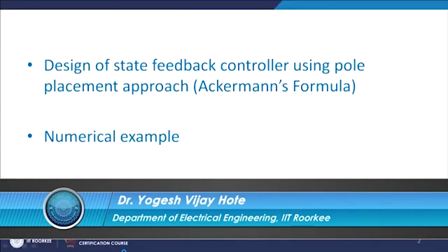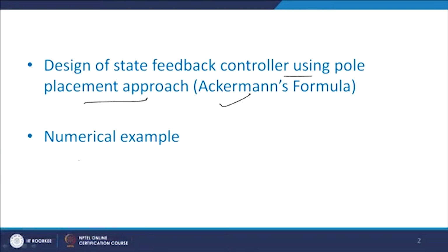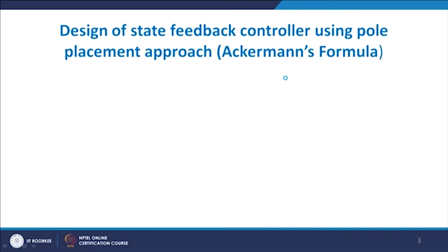We start with pole placement by state feedback, part 3. In this we will study the design of a state feedback controller using the pole placement approach, that is Ackermann's formula, and whatever technique we study will be based on Ackermann's formula. That means we will solve a numerical example based on Ackermann's formula.